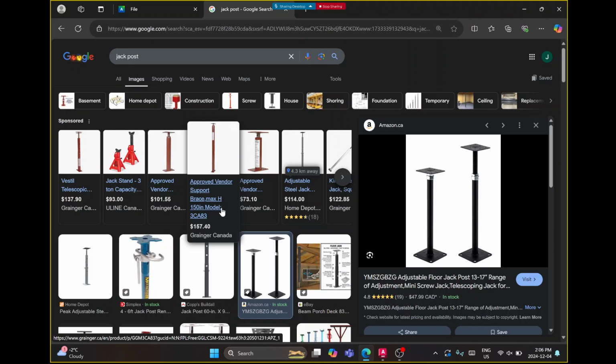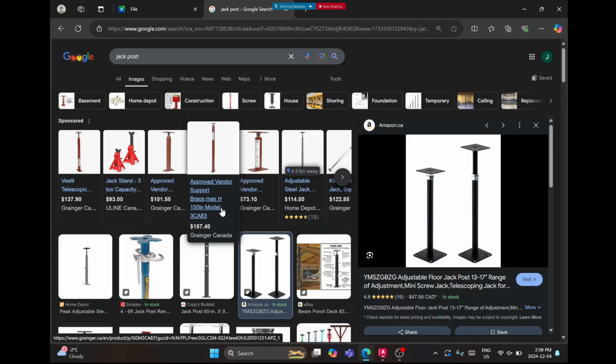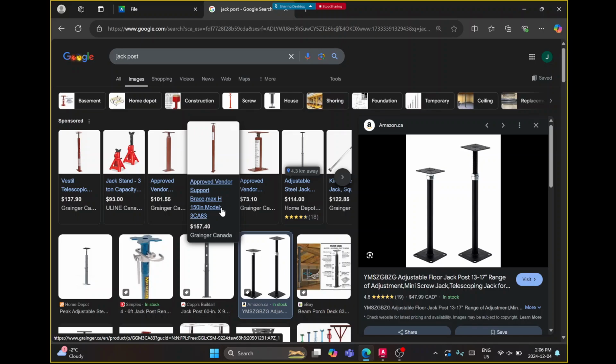But what you're supposed to do is get a custom made steel post. You go to a fabricator and get it based on a very detailed drawing. Not detailed, but just very accurate down to the 10th of a millimeter or whatever. And they'll build you a post. Even the ones that are built look kind of like this. This is round, they'll build a square post. You have a base plate and a top plate. And usually the top plate and base plate will have holes in it so you can drill it into the concrete or the wood. And the same thing with our post.